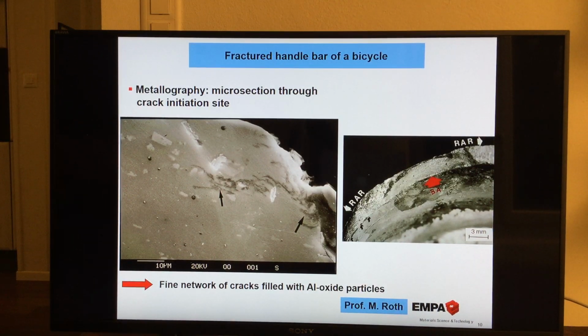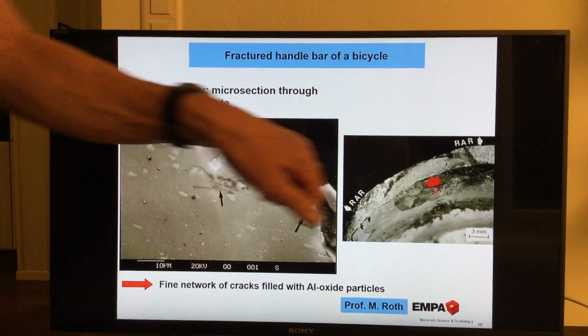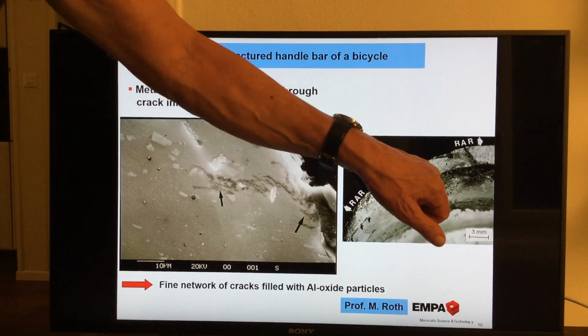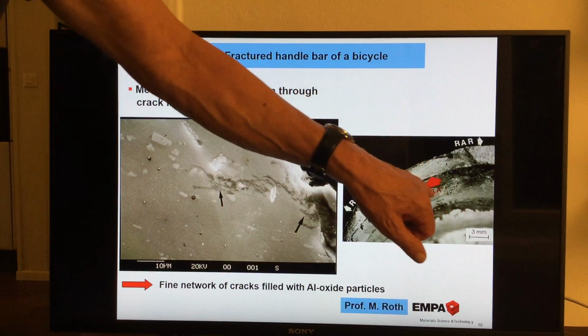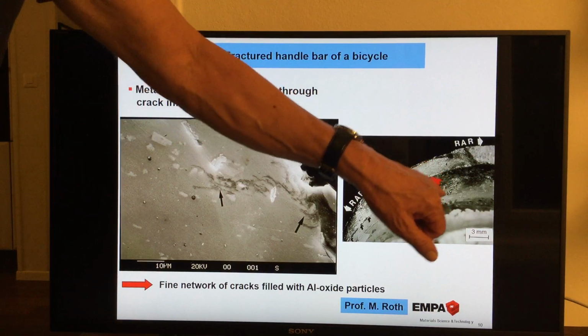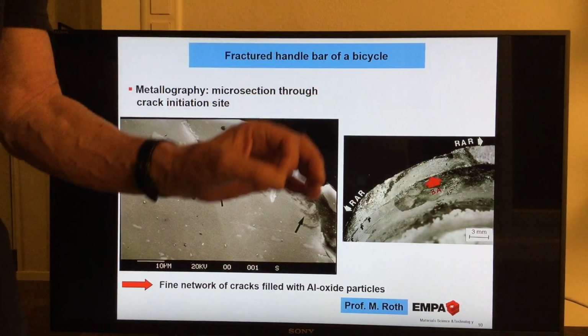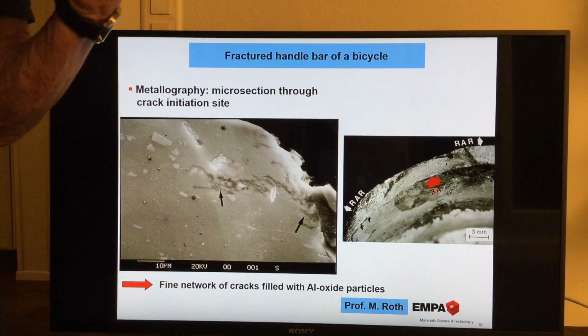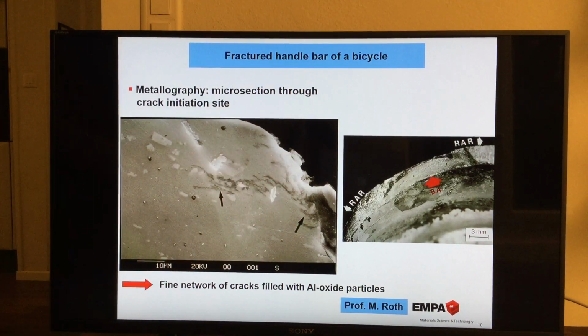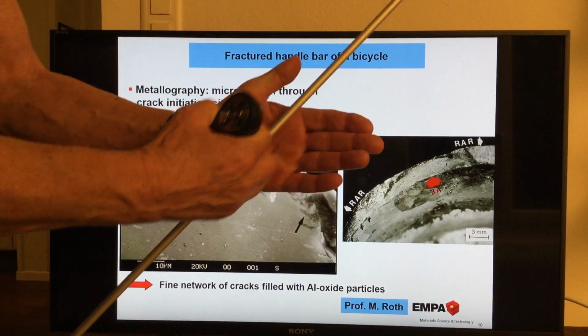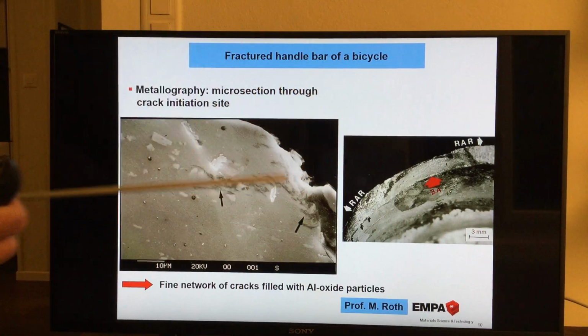You can imagine the aluminium oxide is embedded. Here the self-protecting coating is destroyed, but it has a self-healing process. So it's again producing aluminium oxide, self-healing, then again the scratching, and again this.